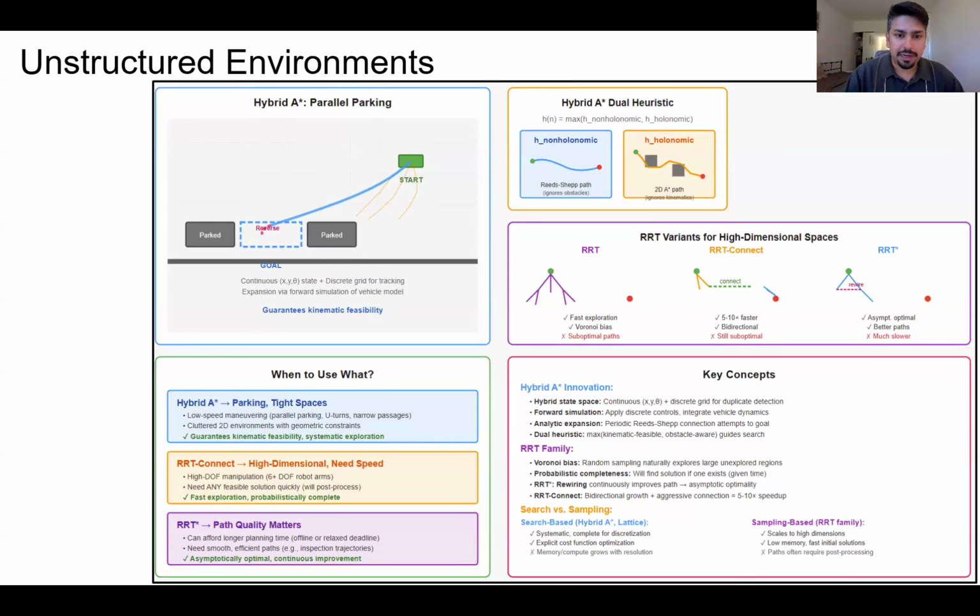And you're ensuring that any kind of action is kinematically feasible. So you go from having kinematically feasible actions and expanding the search. You can also have forward actions and reverse actions. So this will lead you to have very natural solutions to parking problems and multi-point turns, and if you're able to reach the goal and you create this graph, and there is a solution which exists in the graph, in the resolution of the graph, you will end up finding the solution. So we will go into a lot more detail on these things in the bootcamp.